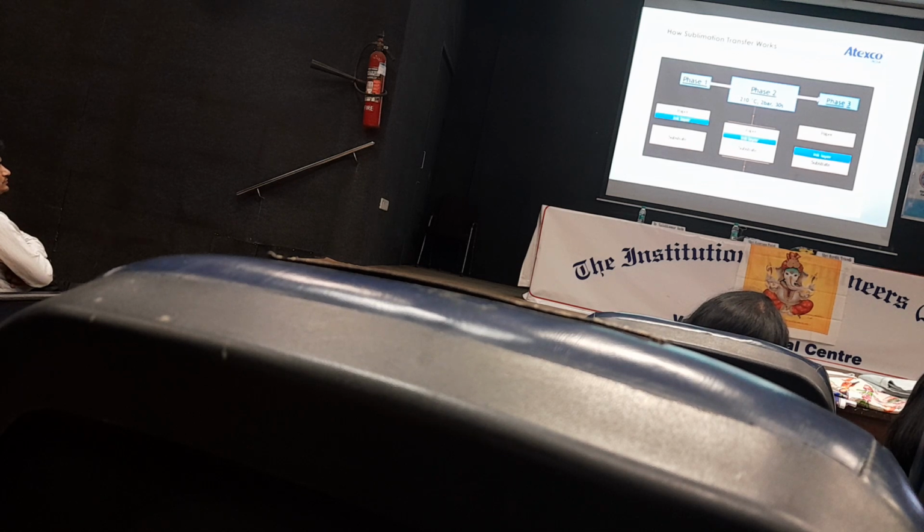In the fusing machine, the fabric goes into the machine in a sandwich format, and then we have to give pressure of sometimes 2 bars, sometimes as per the requirement of the fabric and inks, and the temperature we use is more than 200 degrees, required to transfer the ink from paper to the substrate fabric.